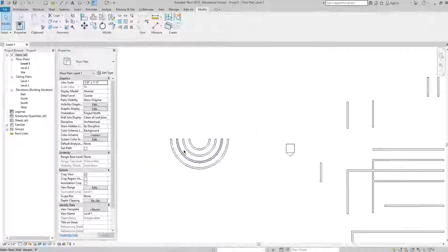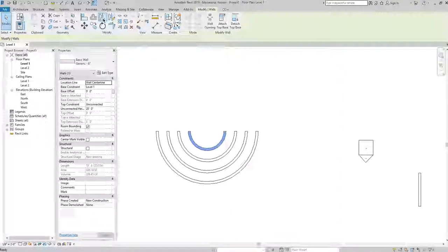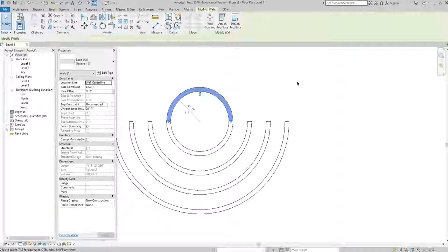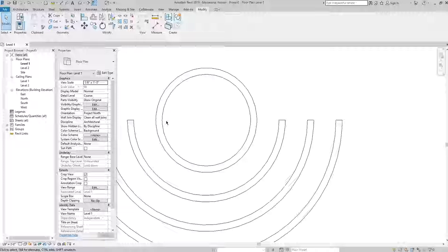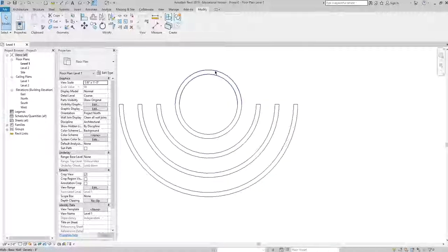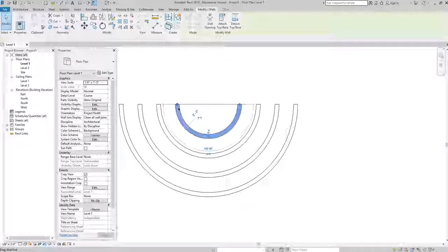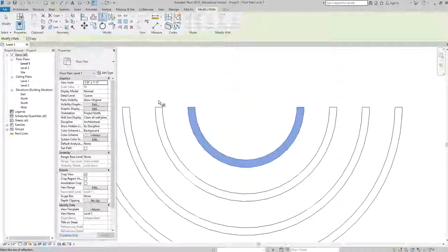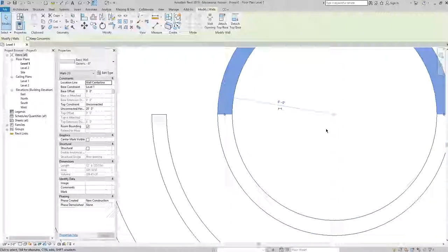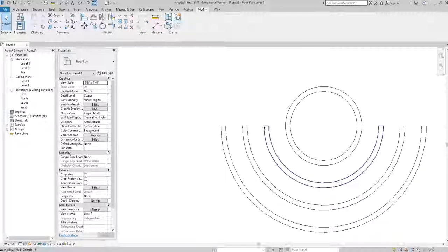Great. Click, mirror with a pick, and it created that second object. My axis at that point was just the edge of that line right there, so it mirrored about the edge of that line. So that is mirror with a pick. Let me delete that. Mirror with a pick. See how I click, and it mirrors about that axis. So I picked just that edge of that line, but that sort of invisible axis extends all the way across here.